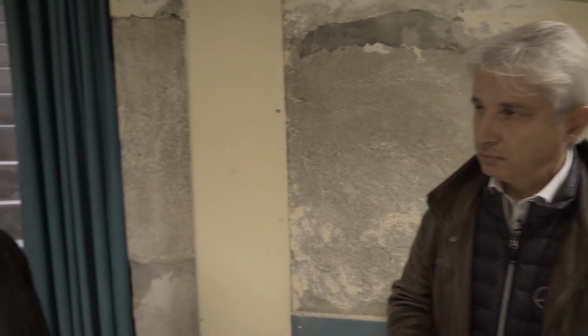It will also be necessary to ensure good air renewal through ventilation. I see that you have an existing system. It will therefore be necessary to check the performance of this system and to adapt it if necessary. Okay, ventilation is planned to be dealt with in the renovation phase. That's perfect. It will therefore be important to ensure the consistency of the renovation work and of the corrective actions with regard to radon rising from the ground.